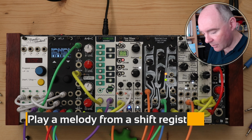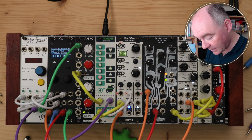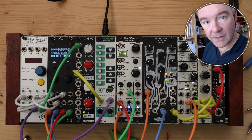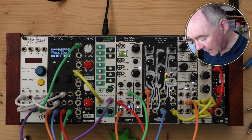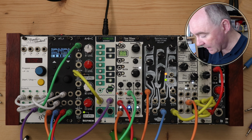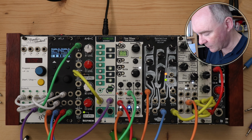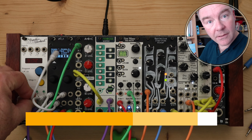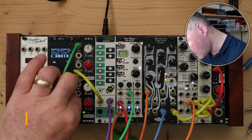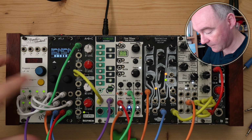Let's use the Enigma Jr Turing machine on the right-hand side now to actually play a melody rather than just modulating the values in the BIA. So just like in previous examples, I've patched this up so that the pitch output comes out of output A, and I'm generating a gate out of output B. Normally you'd probably put an envelope in there, to trigger with the trigger output, but we'll just use the gate for now. We're going to send a random CV value from output 3 here on Palms into the CV2 input here on Enigma Jr on the right-hand side hemisphere.